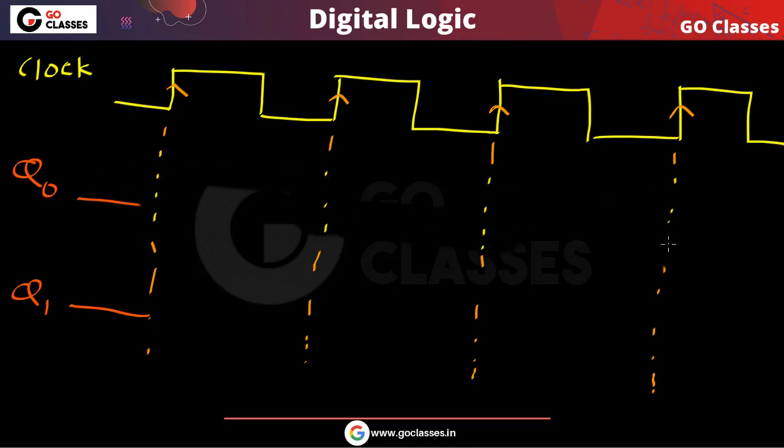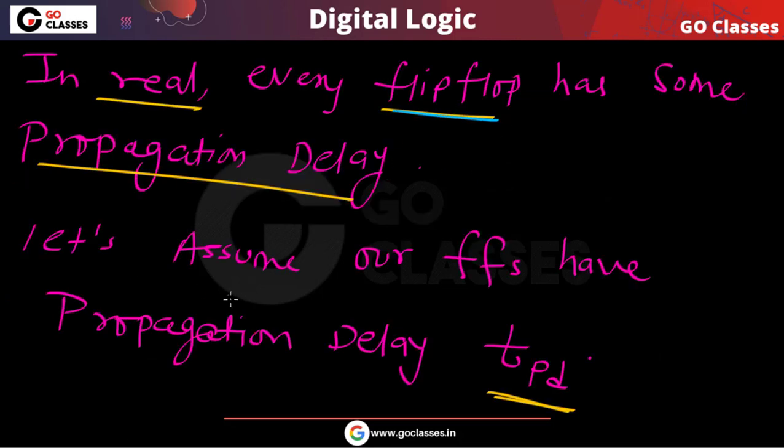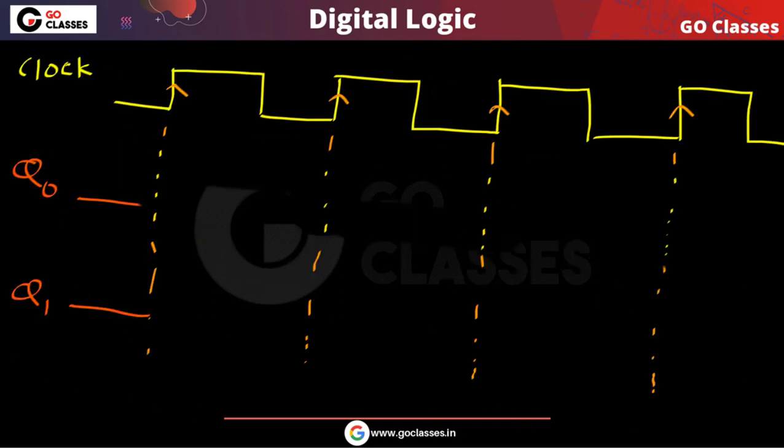In real life, every hardware, every digital circuit, has propagation delay, so let's assume the flip-flop also has propagation delay TPD. With every rising edge of the clock, q0 will toggle. Initially q0 is 0. When the clock goes from 0 to 1, q0 will definitely toggle, but after some time, because there is a propagation delay.